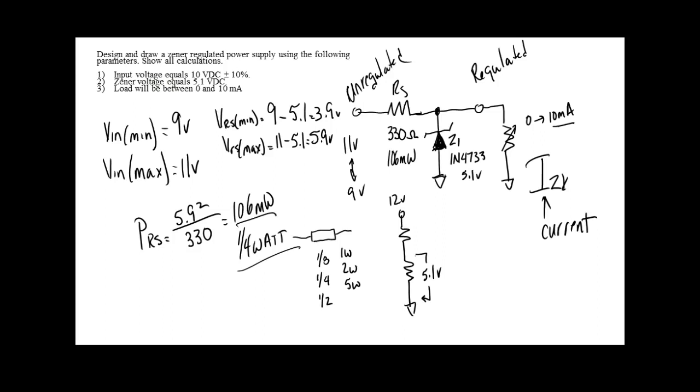And how can you tell the wattage rating of the radial lead resistor? How do you know the wattage rating? Not the color. It's not color coded. The value is color coded, but the wattage rating is not color coded. So this is something you need to learn too. You need to be able to look at a resistor and tell what value.